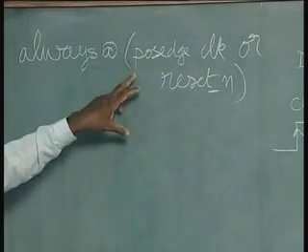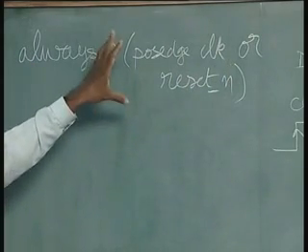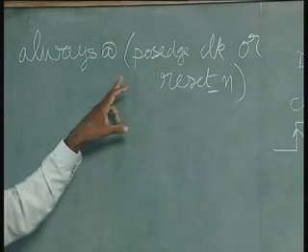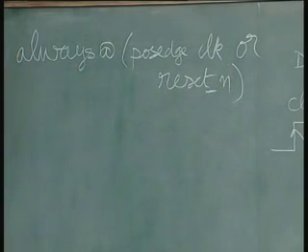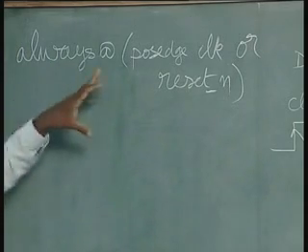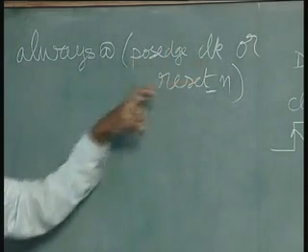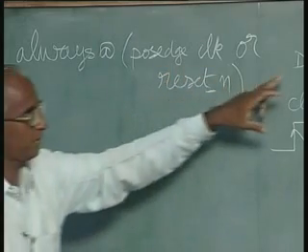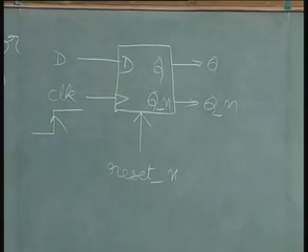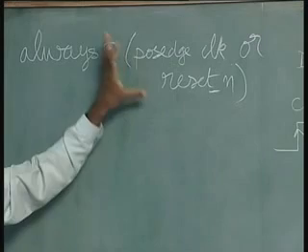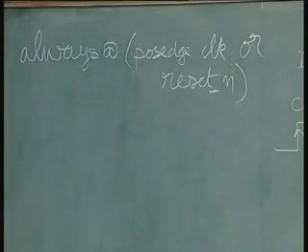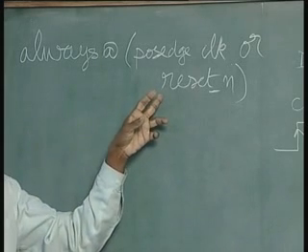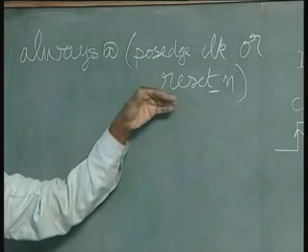Basically, the inputs pertain only to the clock, and notice that D is not appearing here. So this indicates a sequential circuit. What makes the difference is that in the earlier combinational case you would have actually put D. Here you only list the edge transitions, namely the clocks. And reset is strictly speaking not a clock as such, but it has a very special meaning.